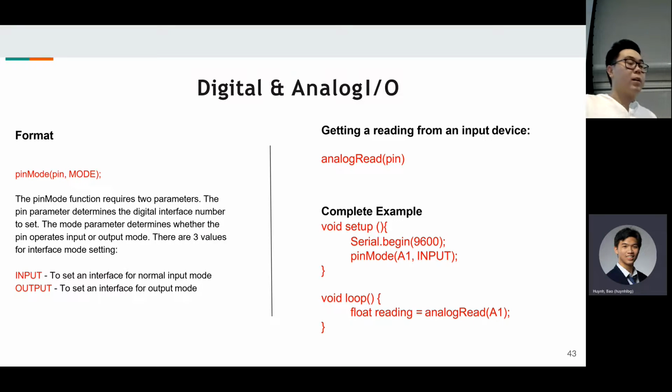And so when you do get sensors, you do have to initialize the pin that you're going on. Since most of the time they use digital pins, you would have to do something called pinMode, where you'd set up the pin that you're attaching your sensor to. For example, you're choosing digital pin number 2. You do pinMode(2, and then the mode that you're doing, so it would be INPUT or OUTPUT. If you're getting data from your sensor, you do input. But if you're sending something out to, for example, a screen, you'd want to put that as output.